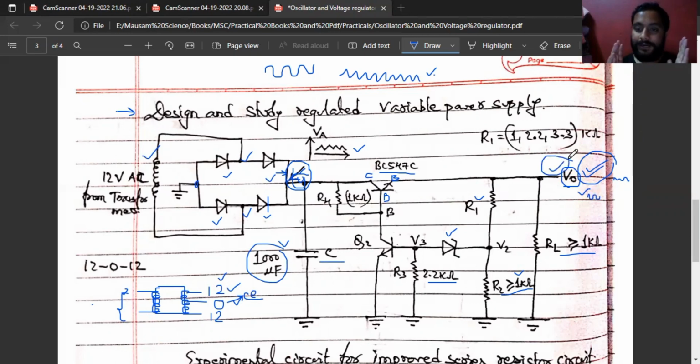So this makes one thing clear: AC is converted here to DC, but a little bit of AC can still be seen with the help of the oscilloscope. But whatever we measure from here, the value of the AC will be less. We can see this easily in our oscilloscope. Whenever we connect it, we'll go to millivolt, and only then can we see the fluctuation of the ripple. We can see ripple over here in the volt range, but here we can see ripple in the millivolt range.